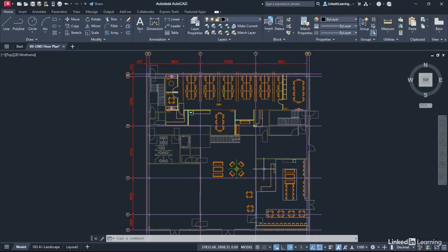But if you've got a really large drawing that you're working on, a massive floor plan, let's say a stately home or a factory, for example, there are going to be areas that you need to go to in that drawing regularly to work on certain things. So what you can do is generate what they call named views. Now, these named views are incredibly useful to allow you to navigate your AutoCAD drawings.